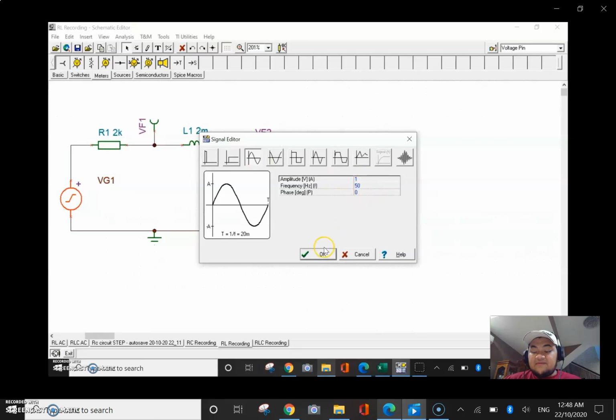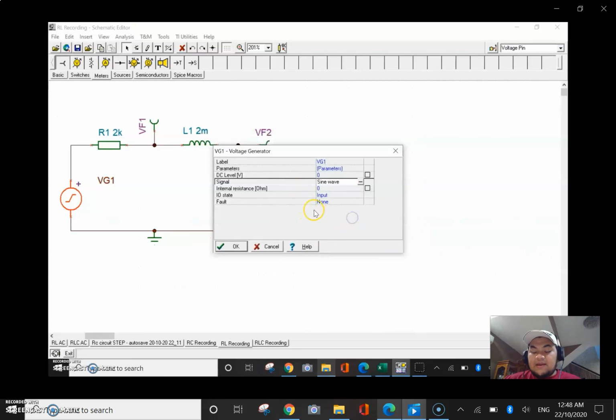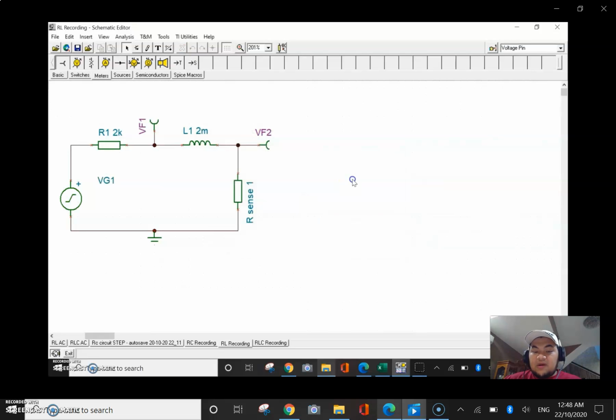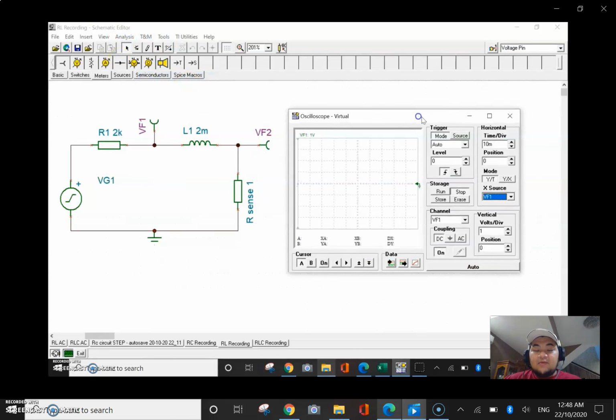Again, now we will observe the waveform using the oscilloscope, but now we will be using normal or automatic mode. Again, we will adjust the axis until we can observe the waveform properly. Now, note that both VF1 and VF2 will produce sine waves, but they appear slightly shifted. From what we learned, we can calculate the phase shift between the two waves by obtaining two readings from each curve that are at the same phase. Here, I will choose the readings of the curve in the first row.